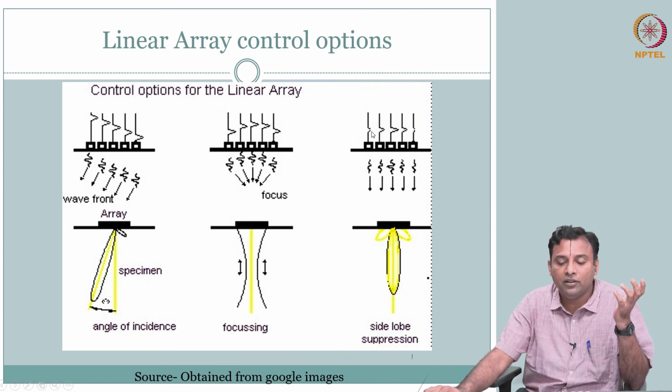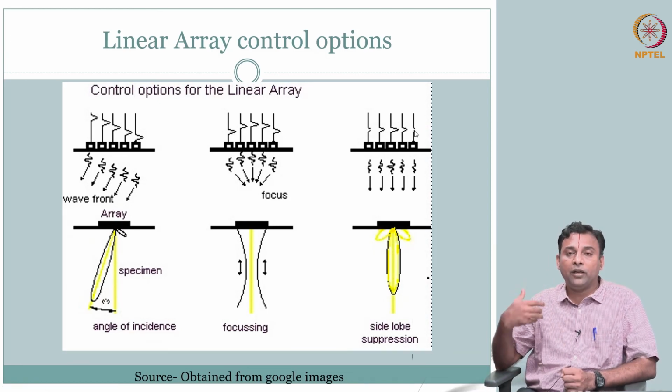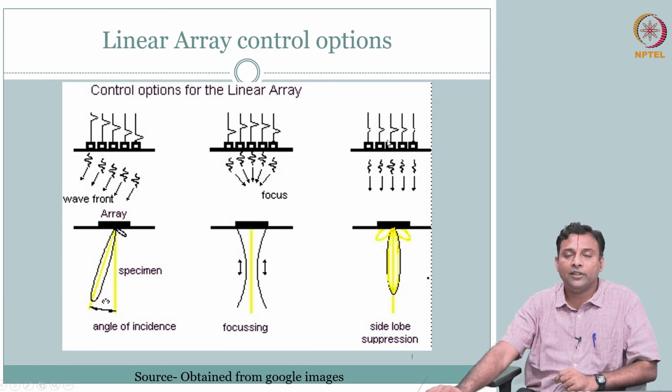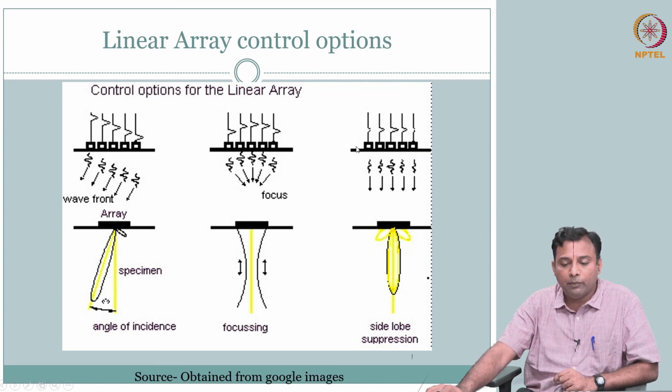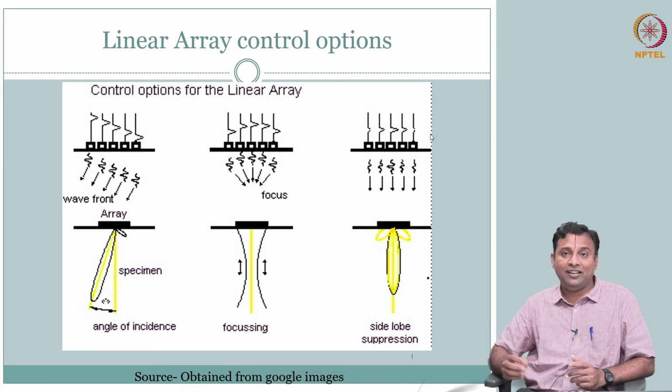Based on that, I can give the amplitudes at the transmit itself. So here I have a higher amplitude, and as you go to the sides I have a lower contribution. In some sense, for transmit apodization you can excite the way you want; you can try Hamming, Hanning, whatever you want. There is no fixed apodization material, because I have control over all of the crystals separately, independently. I can give the same waveform at a different voltage, and the profile of this can be your window function. Clear? It is all electronically done, and that is that.